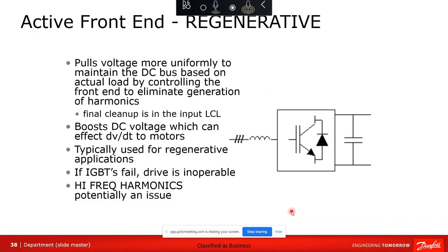One option is a brake resistor, which is fine. You just blow off that extra energy as heat, and it's wasted. But another option, which is kind of cool, is you can take that energy from that regenerative load and put it back on the grid, which is kind of cool as well, because now you're regenerating electricity. Engine test stands, generator test stands, lifting systems, cranes, hoists, DC to DC grid conversion systems. Those are great. Shaft generator systems and shipping, those are perfect.